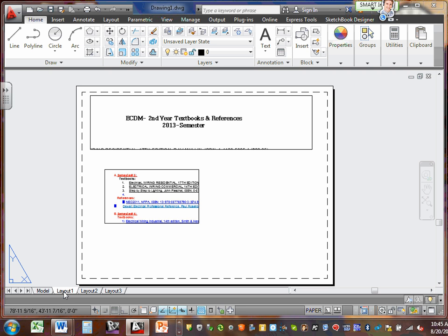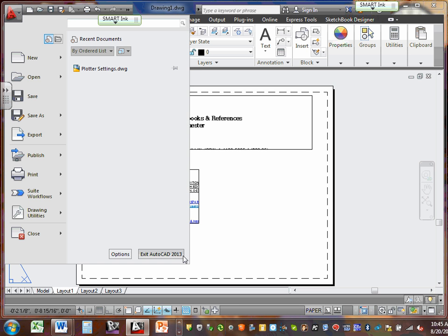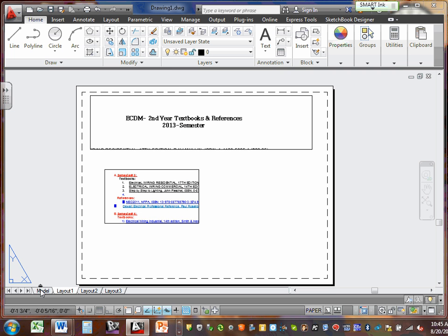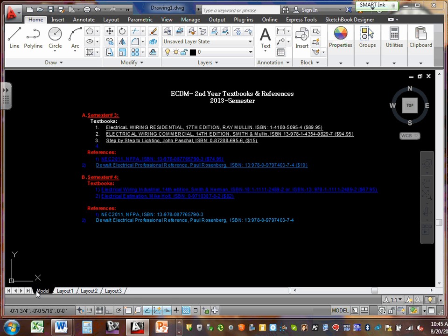We'll talk about scaling the viewport and all this good stuff. And then we talked about when you go to options here, how to do certain settings for your CAD when you start working with it. So between the options on the settings, the paper space, the model space, and also the icons at the bottom here that you can use to set up ortho or snap to object and so forth.